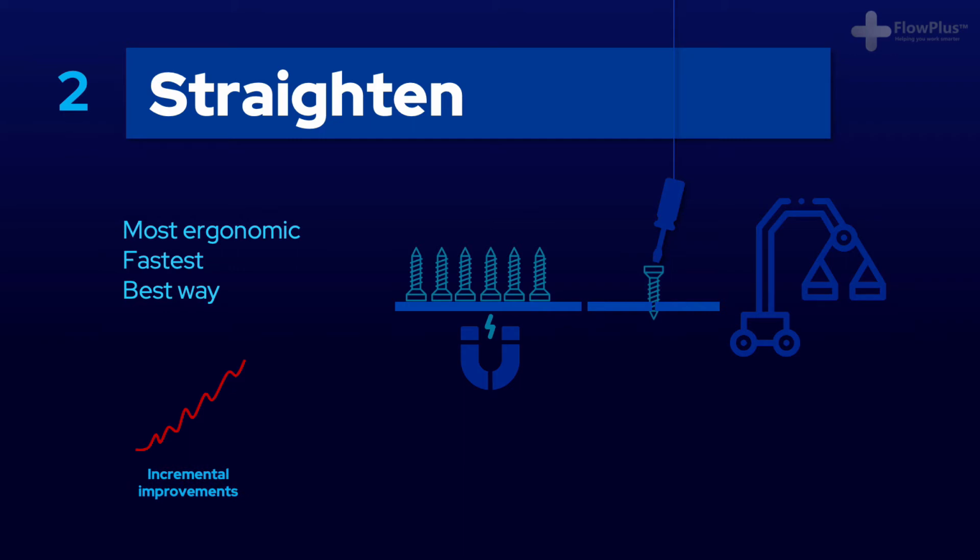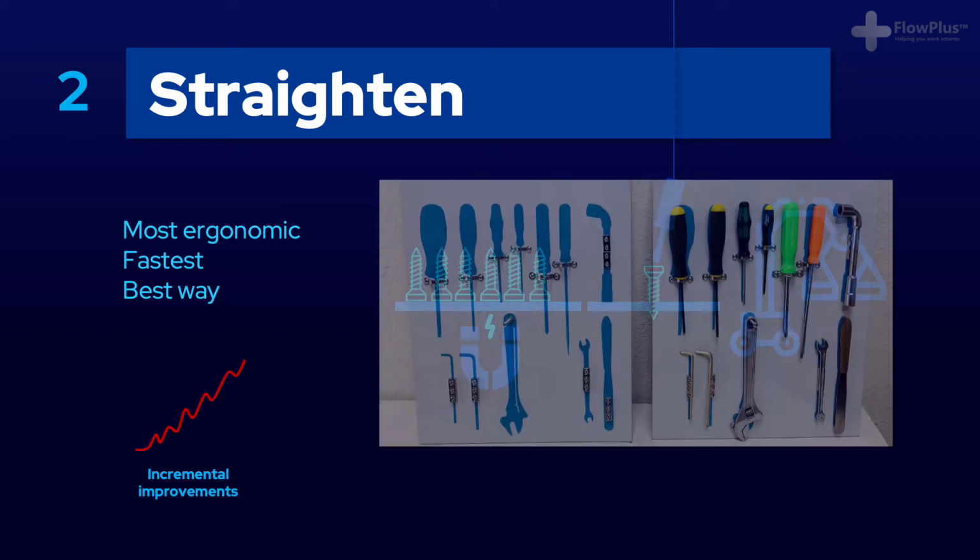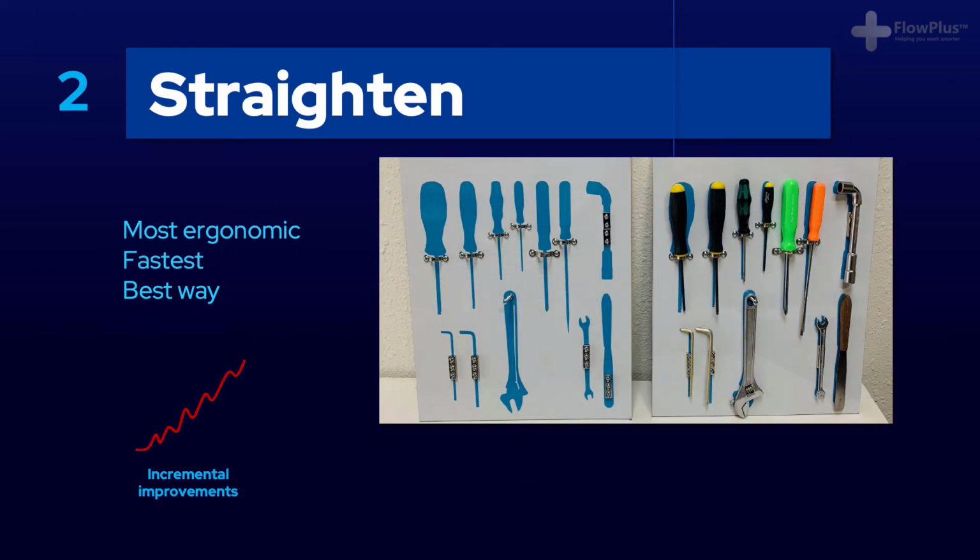Best-in-class manufacturers have demonstrated the huge benefits that can arise from very small, highly repetitive tasks. For example, by lining a table with foam, picking up small items becomes marginally faster as your fingers can press into the surface and get better grip. If this operation occurs 50,000 times per day, then these improvements soon add up to create large time and cost savings. It is worth mentioning something called shadow boards here.